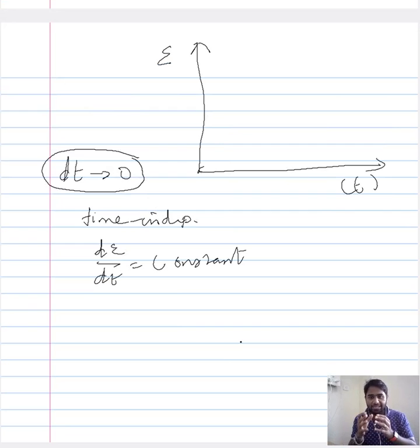But for him, the strain over a small duration of time, which is characterized in this manner, is constant for the different dt's. So if you section the overall time into different time steps, for each and every time step, the amount of strain was constant. So if you make that consideration and translate it to the constant strain rate, then the time independent section plot would look something like this.